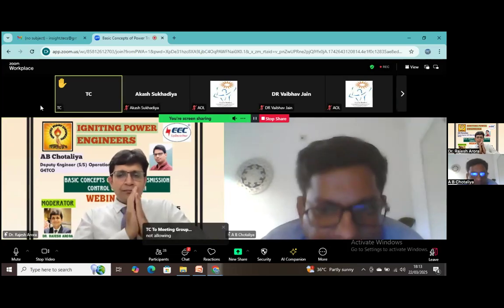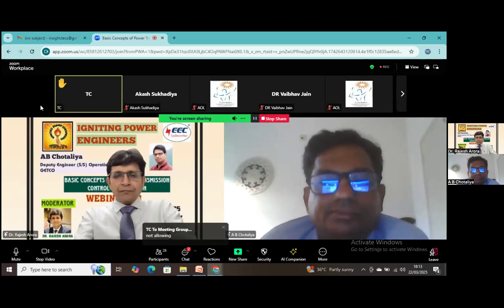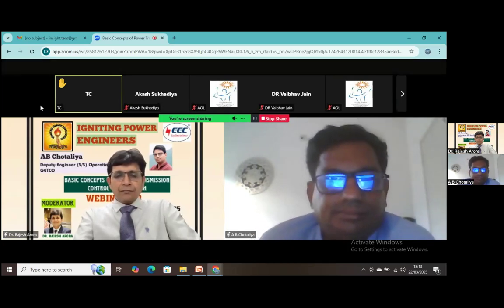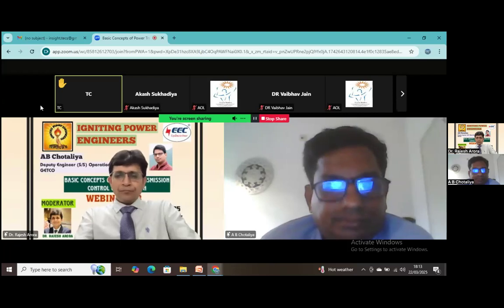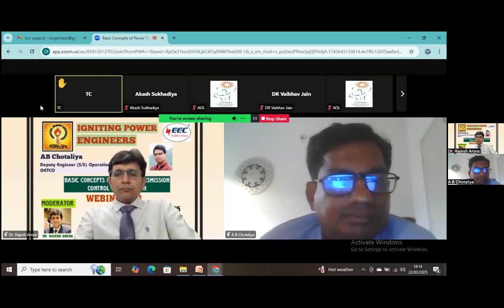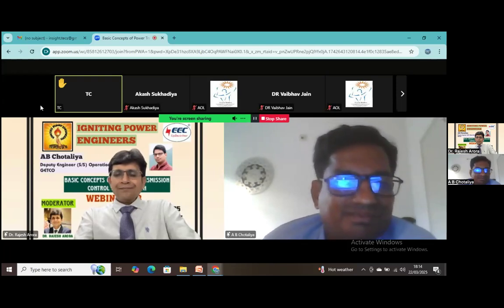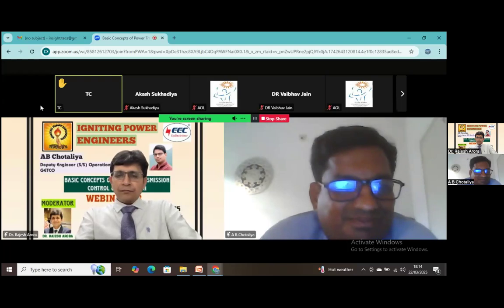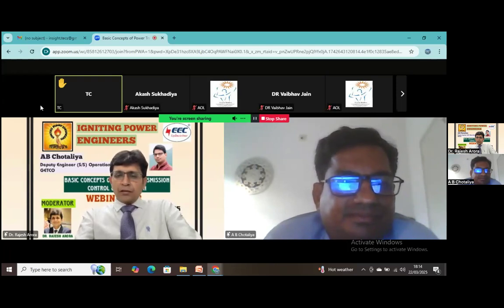My name is Chospel. Just now I've seen in the control circuit that we have used the fuse on the phase as well as on the neutral, I mean the negative side. Quite often nowadays people are using MCBs, and there we should opt for a single pole MCB or a double pole. In case of single pole, they prefer to have a neutral link, obviously. But is it right to disconnect the neutral, sir, in double pole?